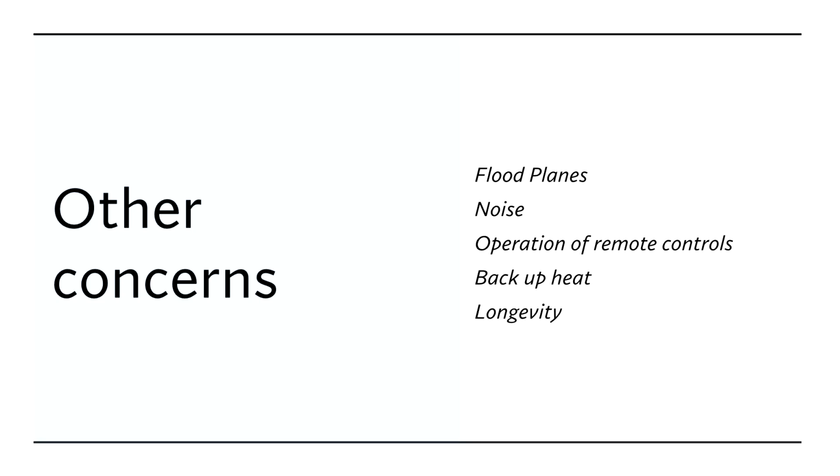Set the fan speed on the indoor unit at the level that you can tolerate as background noise, but not fast enough to make you want to turn it down all the time. And then set your temperature where you'd like to have it be that's comfortable. It will take you some adjustment to get used to what that number should be, but generally what you're going to find is set it and forget it.